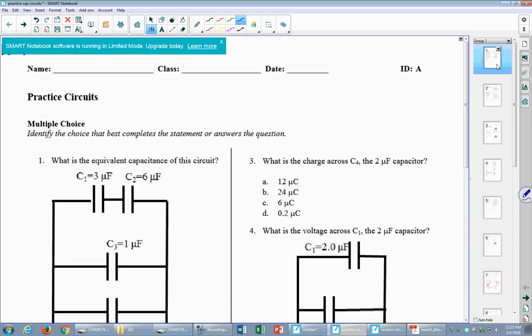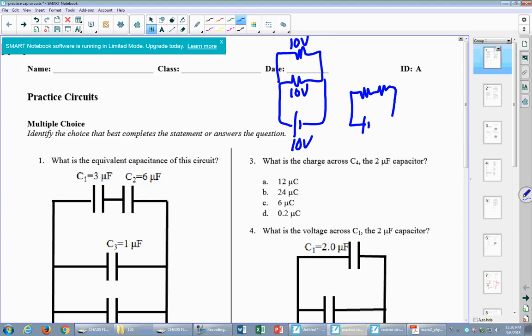Good question. So parallel circuits give off more light because if I have two resistors in parallel, say they're identical, across a 10 volt battery, I get 10 volts across each of those resistors. But if I have those same two resistors in series, I don't get 10 volts across each. I get 5 volts across each.